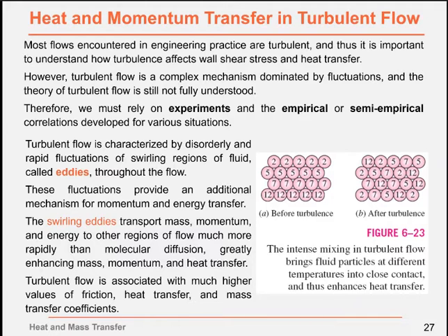We name those eddies throughout the flow. You can see this figure, this example. The intense mixing in turbulent flow brings fluid particles at different temperatures from two different layers into contact with each other, and thus enhances the heat transfer.